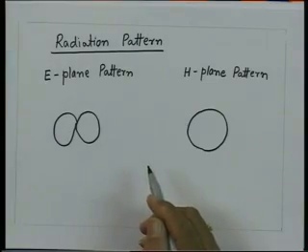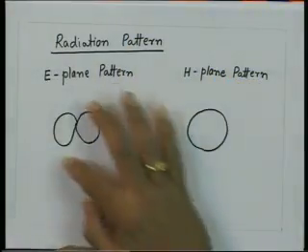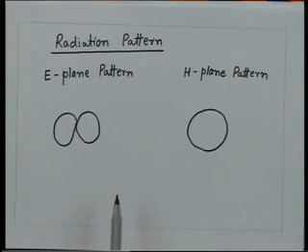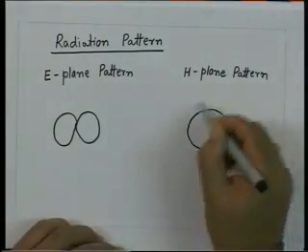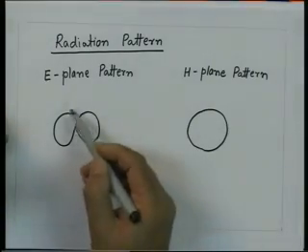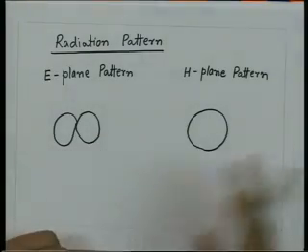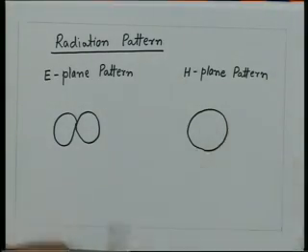So, generally when we discuss antennas, since this figure is very simple, most of the time the radiation patterns are given in the E plane, which is complicated, for the Hertz dipole or for a linear dipole, and because of the circular symmetry the H plane radiation pattern is always a circle. So, in the books essentially we see the patterns which will be this, and it is implicitly assumed that the H plane radiation pattern we know, and that it is a circular pattern.